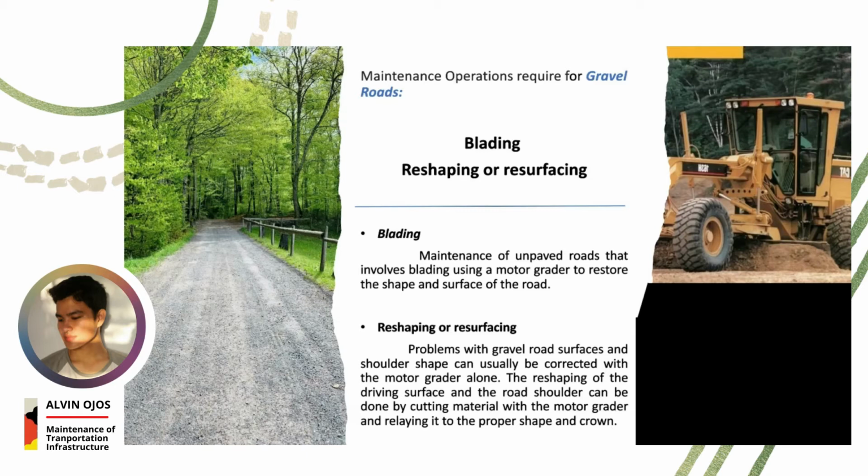Reshaping or resurfacing. Problems with gravel road surfaces and shoulder shape can usually be corrected with the motor grader alone. The reshaping of the driving surface and the road shoulder can be done by cutting material with the motor grader and relaying it to the proper shape and grade.